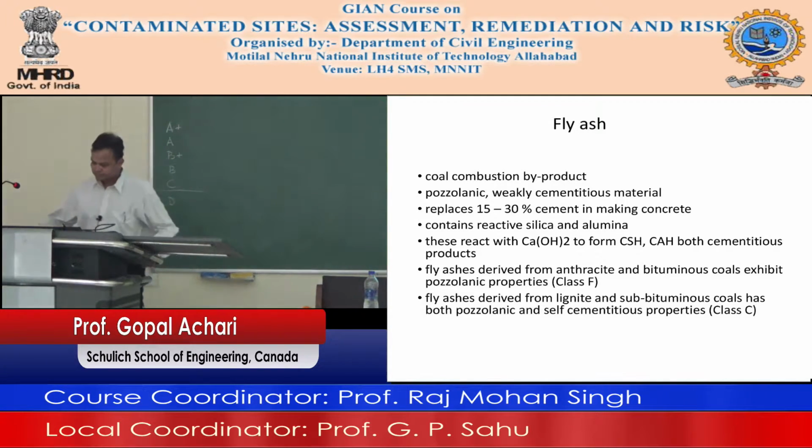Okay, so fly ashes that are derived from anthracite and bituminous coal exhibit pozzolanic properties. Fly ashes derived from lignitic and subbituminous coals have both pozzolanic and self-cementitious properties. What you see in the bottom there is a figure of fly ash particles. They have these little spherical particles in the form of cenospheres. Okay, so see this calcium hydroxide. These react with calcium hydroxide to form calcium silicate hydrate.